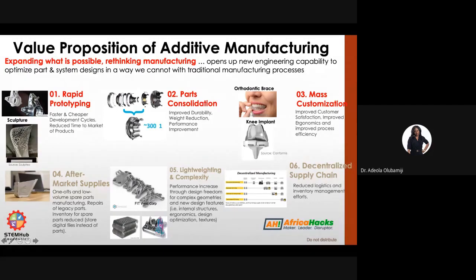What this means is, if those 300 parts, maybe you needed to weld them. Now you don't need welding anymore. You don't need those welded joints anymore because they are all made as one single part. Maybe you needed to bolt them together. Now you don't need that extra bolt that can increase weight. You don't need that anymore. What that is doing for us is helping us with weight reduction, because now you have merged all the parts, no weld area, no bolt. So weight reduction is one of the good things that come out of part consolidation.